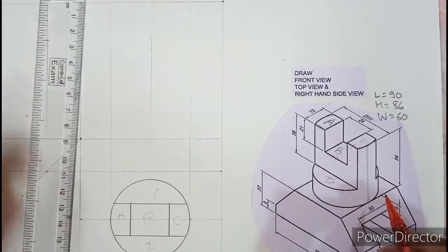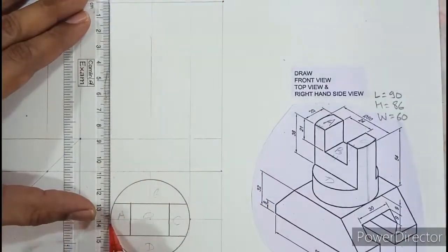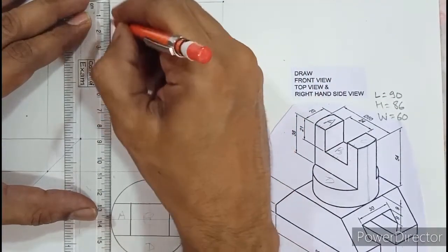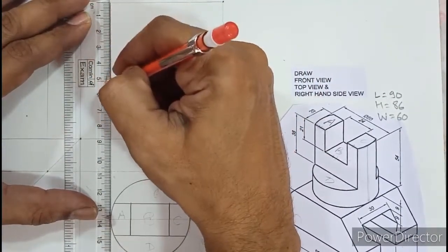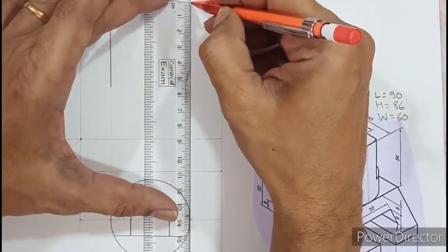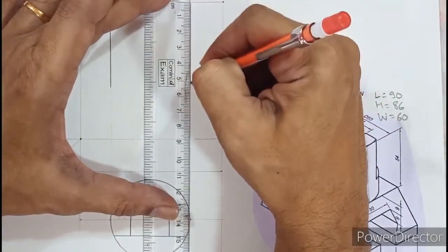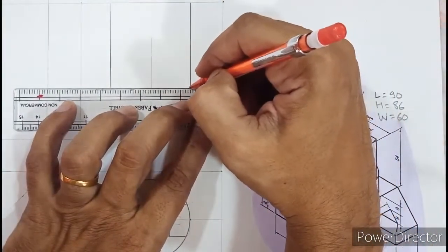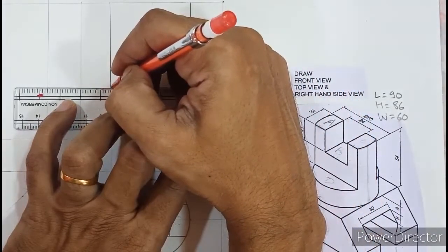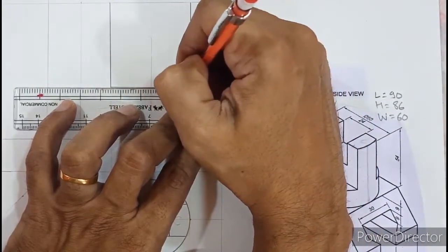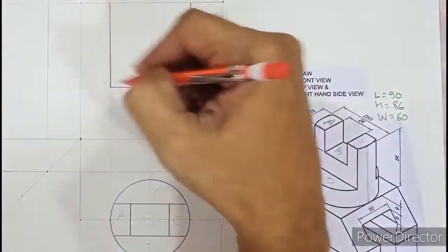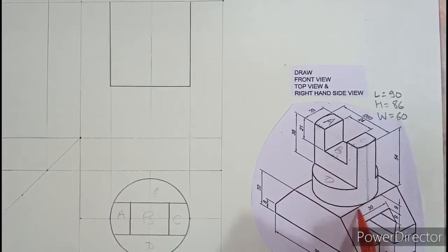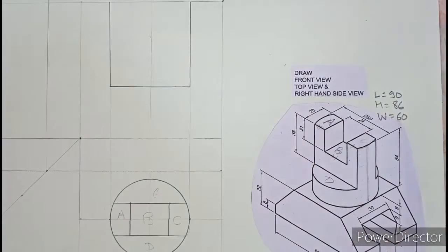So let us darken the boundary up to 54 mm. I will align this with A, and up to 54 millimeter I will darken this boundary. We'll do this on both the sides. Up to 54 we need to darken it. Then this bottom edge I will close down because the circular edge will be seen as a straight line. So I hope these three lines are clear, what they are meant for. It is for this cylinder, then the bottom circular edge, and this top one.